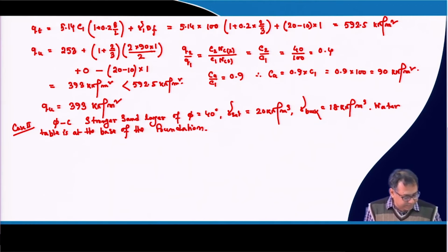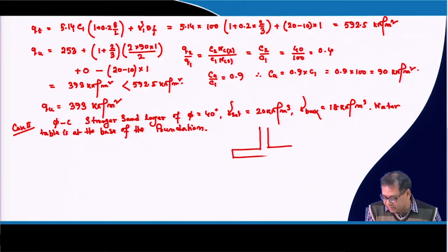So, let us see how we can do that. Before I go to the calculation here, you cannot use the basic equation that I have given directly, because here you have to do some slight modification. In earth pressure there is only the gamma 1 term, but now the gamma will be different, because water table is present. So, let us first calculate the earth pressure, then we will put that value in your equation. I will show you how we can calculate the earth pressure.